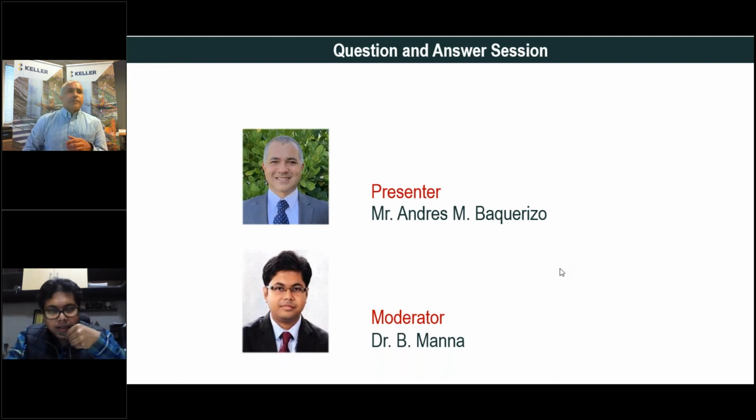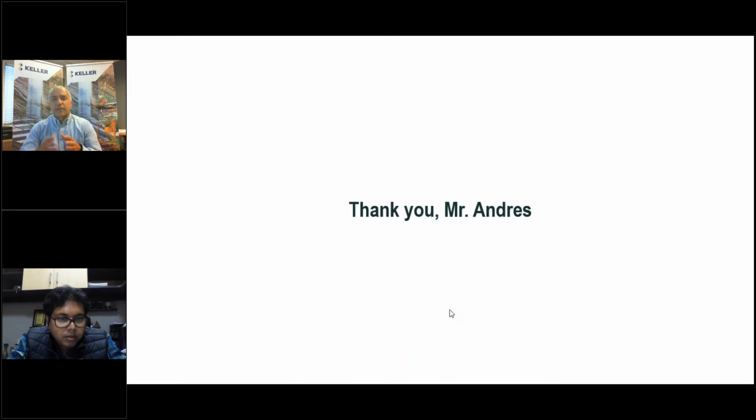So yes. So we have drilled piles all the way up to 1,000 millimeters and 1,200 millimeters. The 1,200 millimeters was installed to 33 meters. The 1,000 millimeters was installed all the way down to 56 meters that we have. So the equipment, of course, was large enough to withstand that. Anything past 1,000 millimeters is typically a fixed lead machine to be able to have enough power to do so.